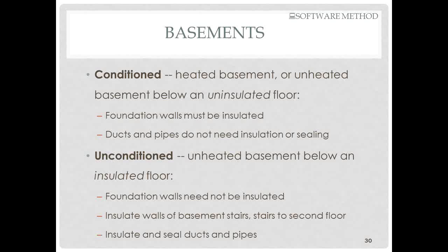If you choose to build an unconditioned basement, you can. In that case, you would have to insulate the basement ceiling, the first floor deck, and also any other building components that separate the basement from the house, like the walls and ceilings surrounding a walk-up stairway, if there's a stairway that walks up to the main house. In that case, you would not need to insulate the foundation walls, but you do need to insulate and air seal any ducts or pipes that are down in that space.